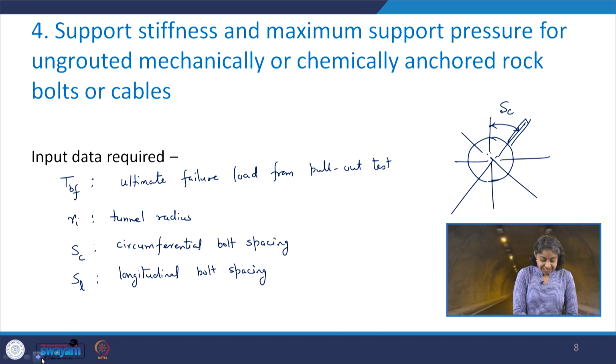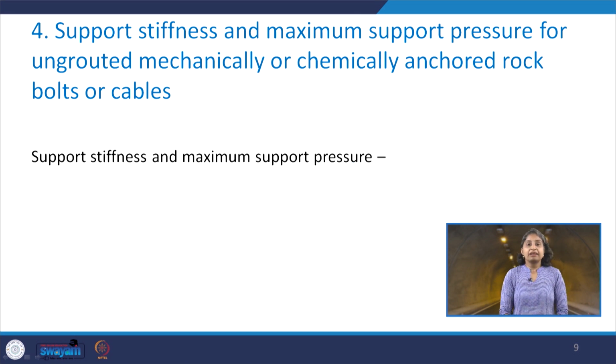So, the next step after knowing all this input data is going to be the determination of support stiffness and the maximum support pressure. So, let us write those expressions here.